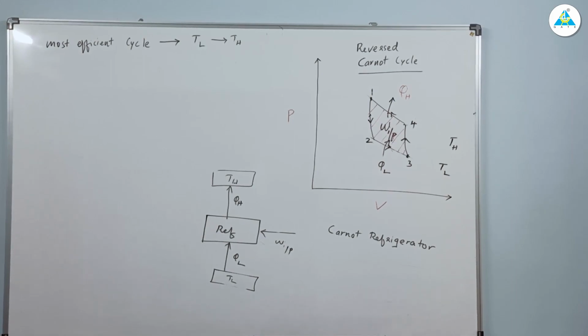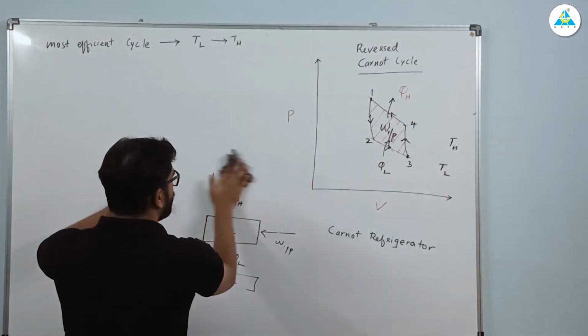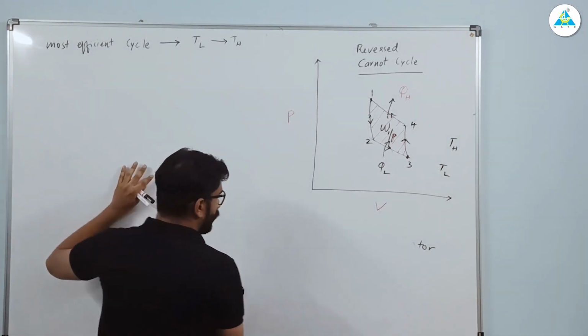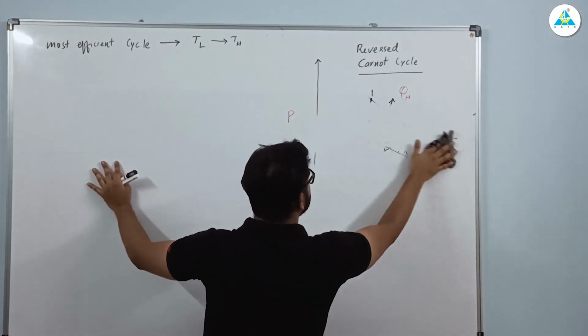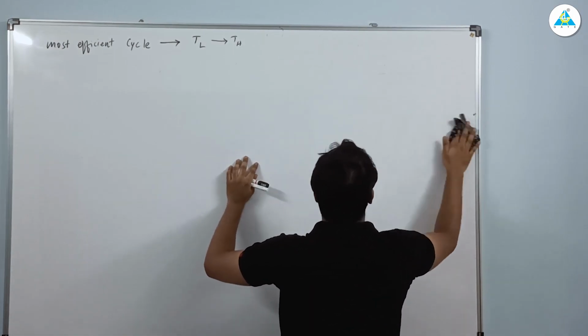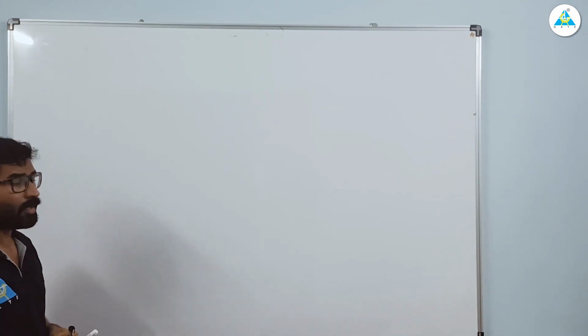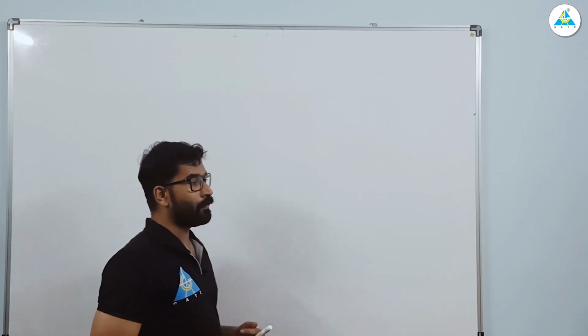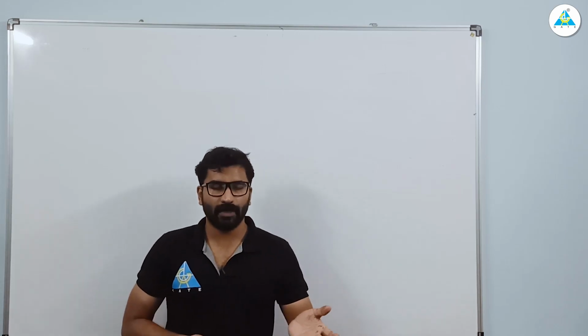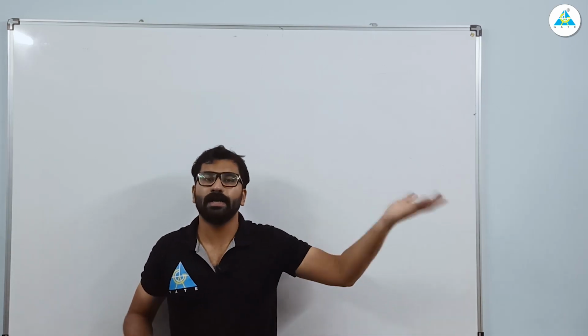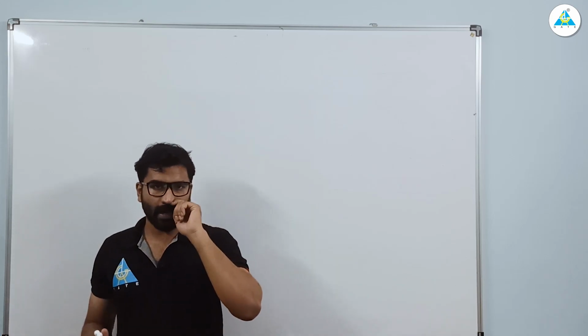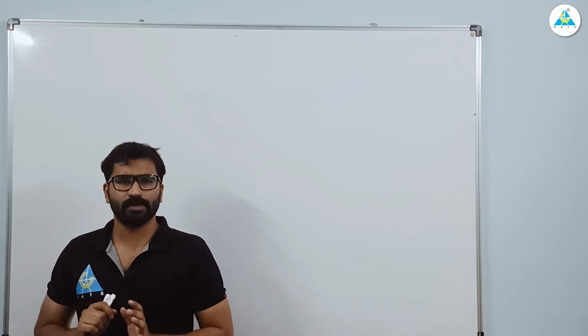Now, what you need to understand for solving questions based on Carnot is the Carnot principle. Carnot did not just develop this system or just give this cycle; he has given some principles. The first principle is, if you have two temperatures, a source and a sink, a reversible cycle will have the highest efficiency compared to all the irreversible cases.